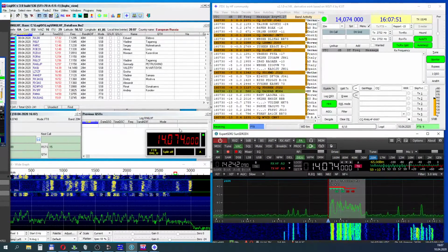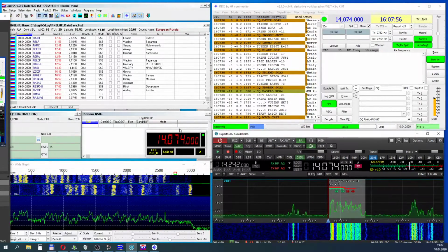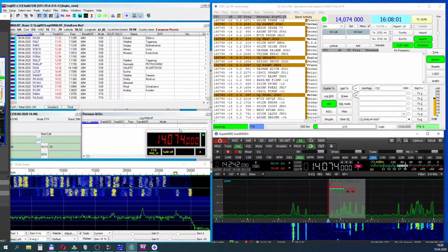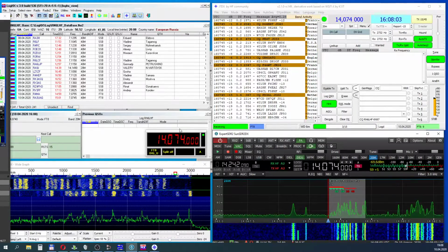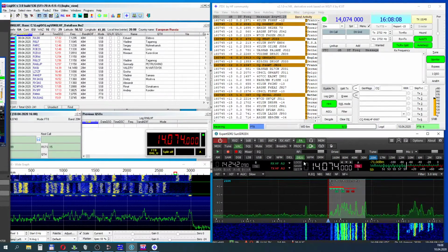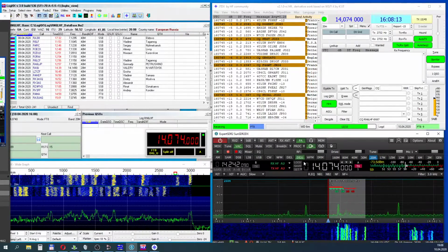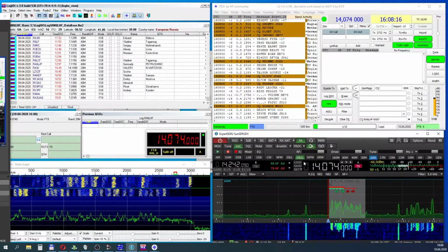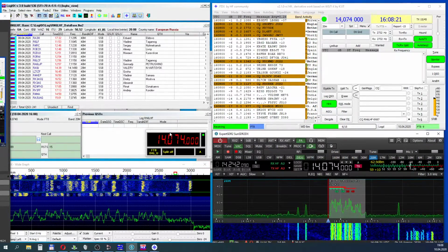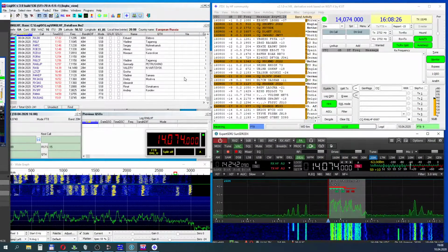The main thing is that we should use two connections. This is audio connections between radio software and JTDX software for sending audio from radio and from JTDX to radio in transmitting mode, and CAT control from logger and JTDX software.